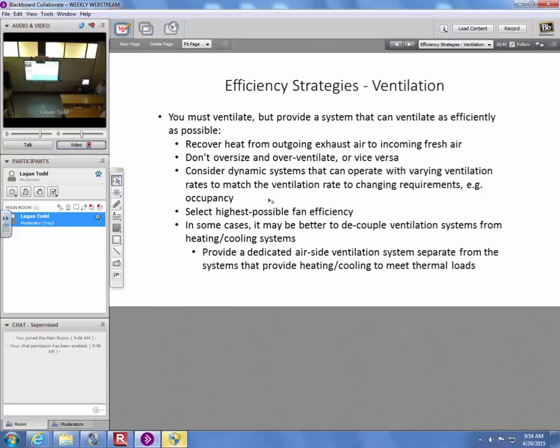And so when Montana adopted the IECC 2012, they amended it in certain ways, and one of those amendments was to say, okay, we get this continuous ventilation thing, but in this cold climate, we're going to let people ventilate some fraction of the time. They just then have to increase the CFM for when they are ventilating.